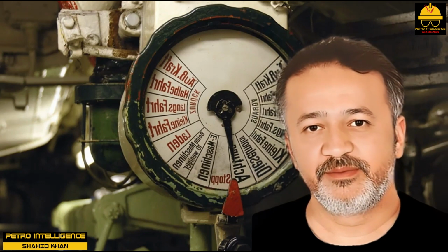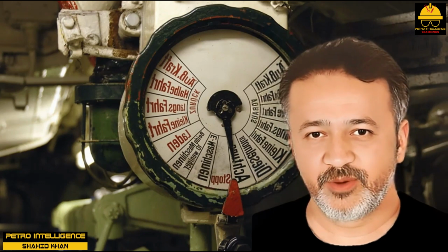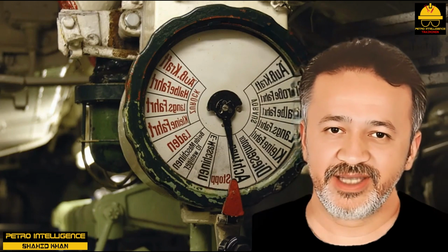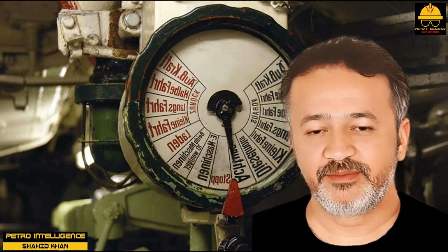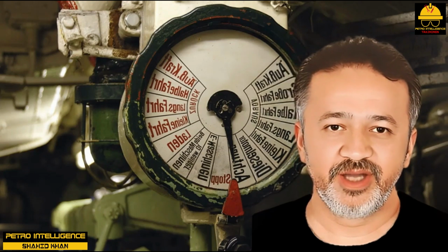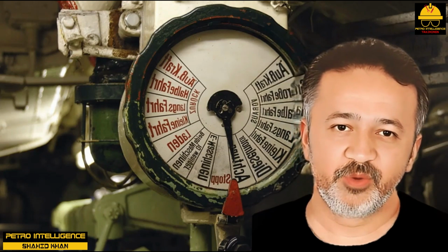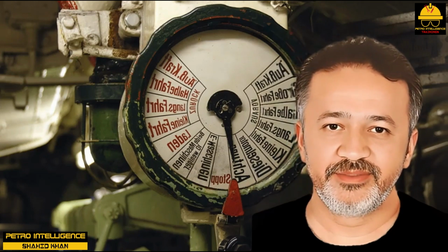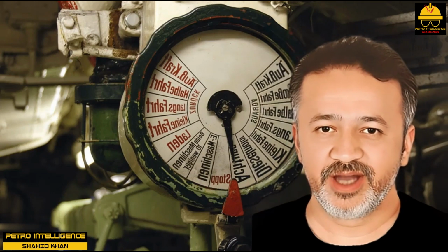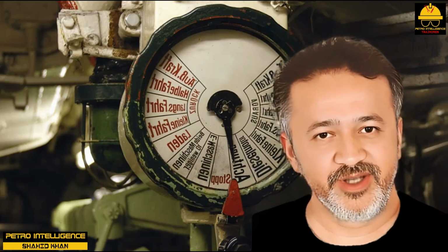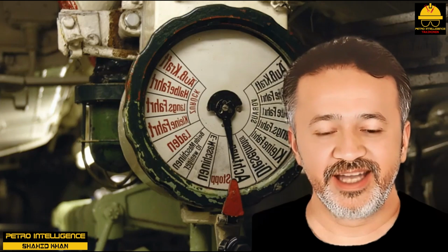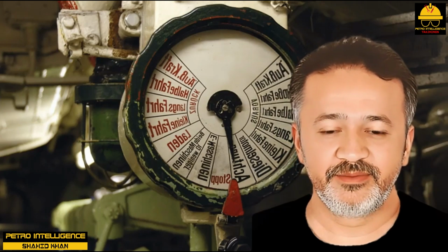Controller modes. Process technicians use a number of controller modes. The most common types are gain, reset, and rate. Gain may be used individually or in combination with reset or rate. Gain is most frequently paired with reset. Rate is typically applied to temperature control applications. The most advanced system uses a combination of gain, reset, and rate.